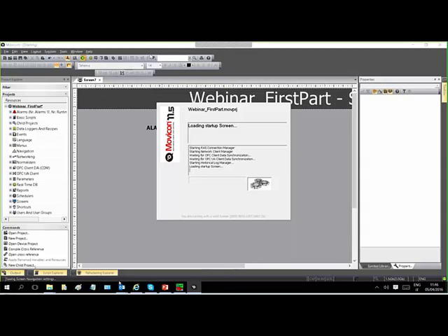And now there is a predefined command. If I click on the object execution, when I click over this object, new command. Now I'm not working on a variable, not working with a screen, I work with the language tab. I select English and confirm my command with OK. And again for the other, when I press new command, language, Italian.